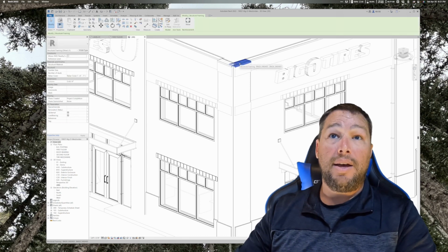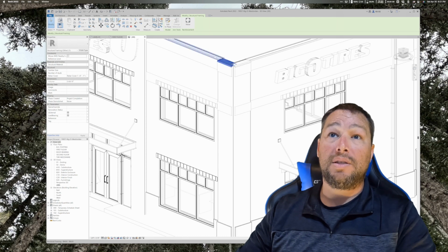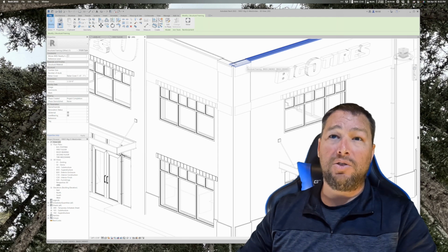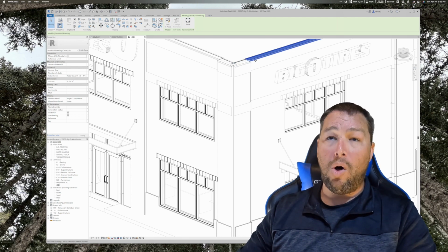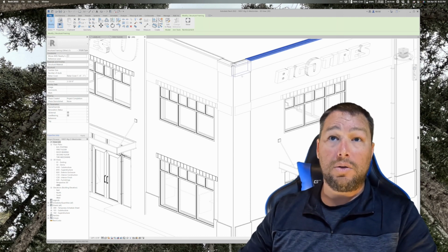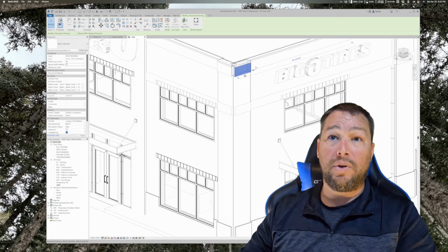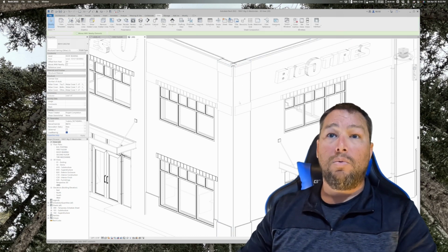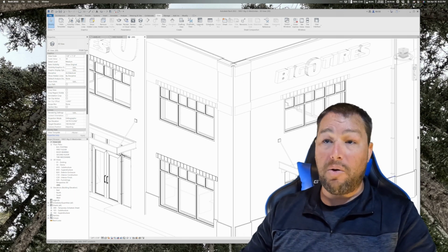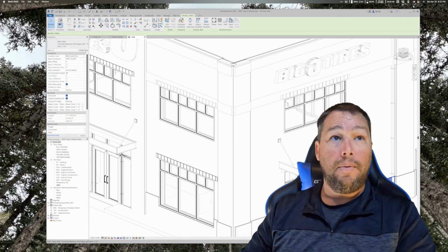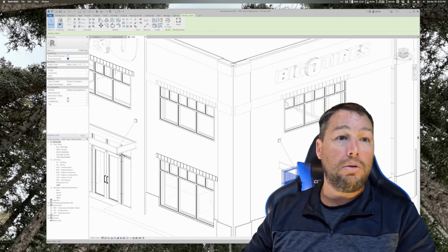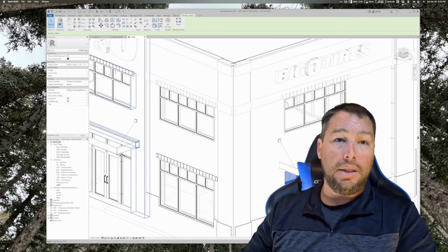So, let's take a look. So we've got structural framing for these parapet caps. In Revit, I thought I drew those, in Archicad, I thought I drew those as complex profile walls, but I might have done them as beams, but I thought I did them as walls. Okay, so that's coming through as a structural framing element. What about this? This should be a wall here. Okay, at least that's coming through as a wall. Okay, curtain wall's coming in as wall instead of curtain wall, so that's not too good. But at least it's there.